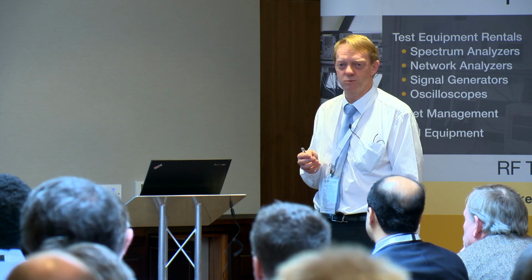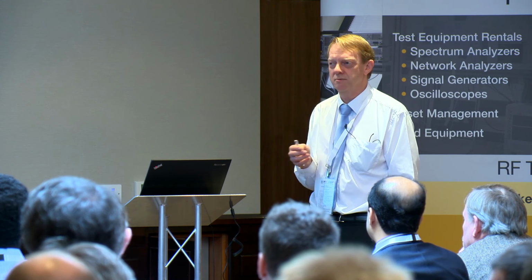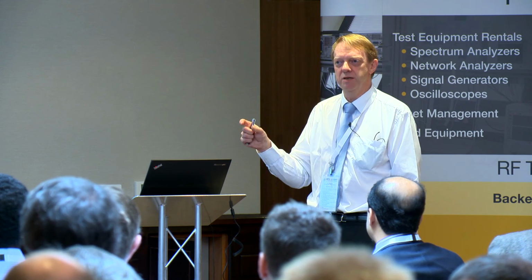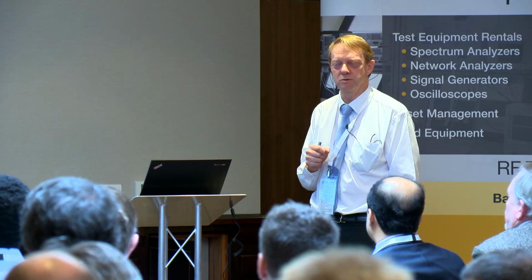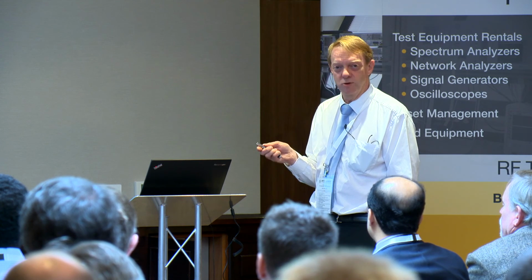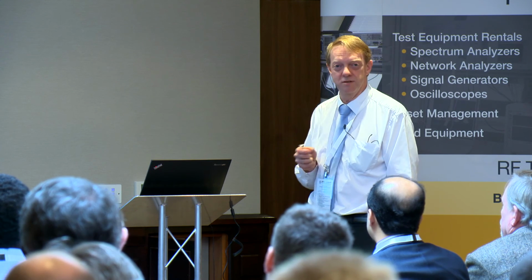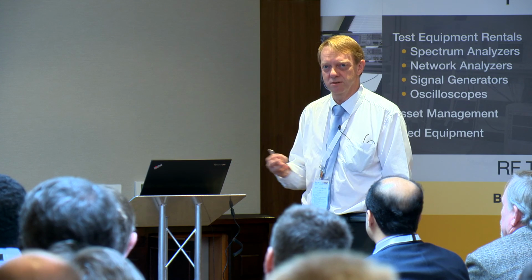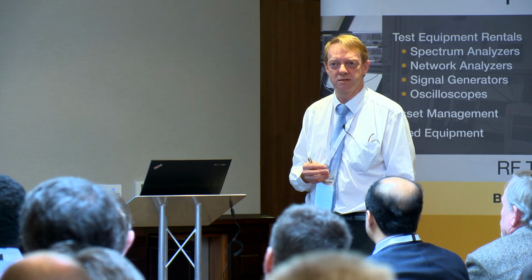You can fail radiated spurious emissions just by placing a GPS device, even if it's not active, close to your GPRS modem. This is avoided if you have this front end filter. It prevents the unwanted picked up signal from getting into the device and then being re-radiated.